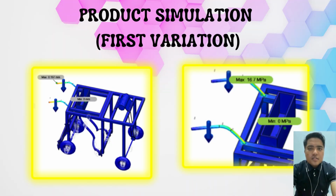For the first design variation, stainless steel is employed on all the main body according to the original design process to ensure long-term endurance. In the simulation, a load of 5 kg was applied to the handle and hopper, which matched the typical weight of a human hand and the energy to control this seed sowing machine.